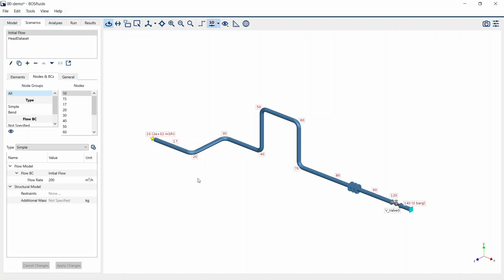you'll need to have that flow rate and the velocity correct. So what you would do is create a steady state analysis. You put in that flow rate, and you'll get from that analysis the actual pressure over here, and then you'll start a transient analysis where you'll change this boundary condition from flow to a pressure boundary condition, and that will correctly have you calculate that water hammer event.